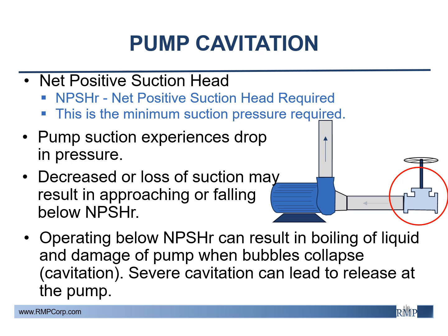If it goes below, the liquid can begin to boil. When the bubbles collapse in the pump, they cause damage to the metal. This is called cavitation. And if it persists long enough and is severe enough, it can lead to a release and a potentially hazardous event.